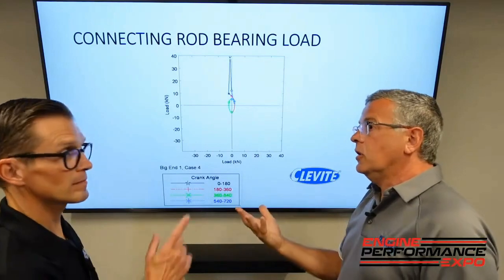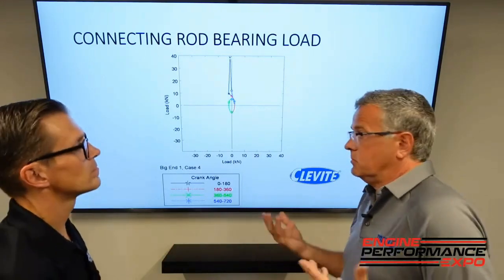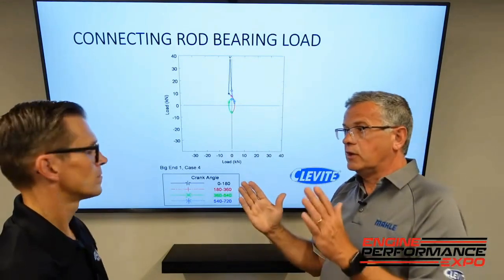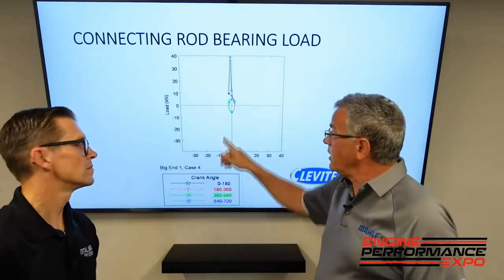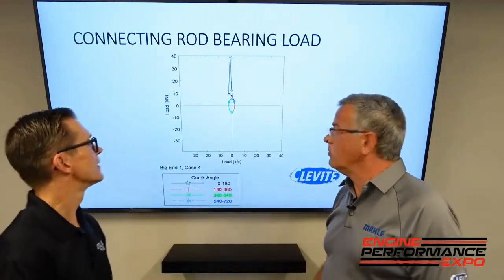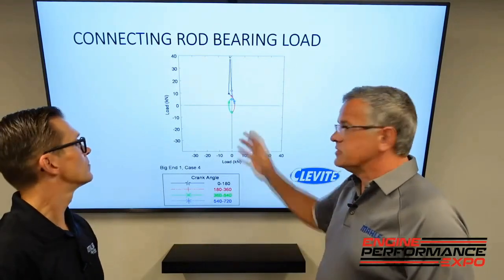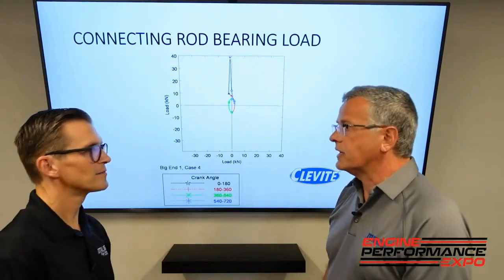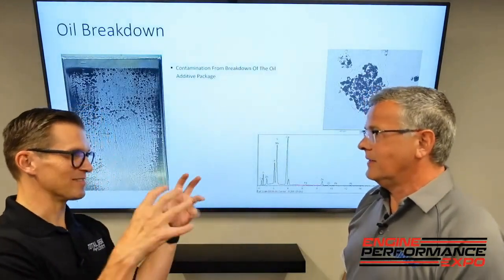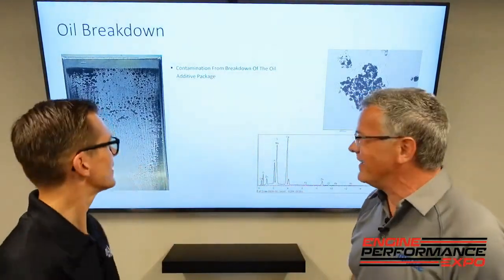So if you upgrade power, with power adders, bigger, nicer cylinder heads, camshaft, whatever it might be, and you didn't upgrade your rods, you can change that to the point where you can pinch off oil flow and lose the oil film, by not having a sturdy, strong enough rod to withstand the movement of the connecting rod. You can see that in the plate engines too. They got everything so light that the rod was like spaghetti. Yep, absolutely.